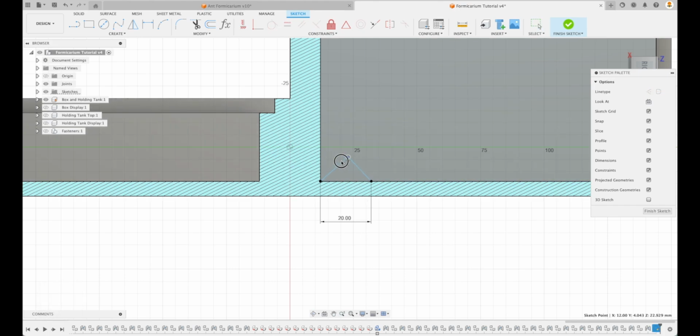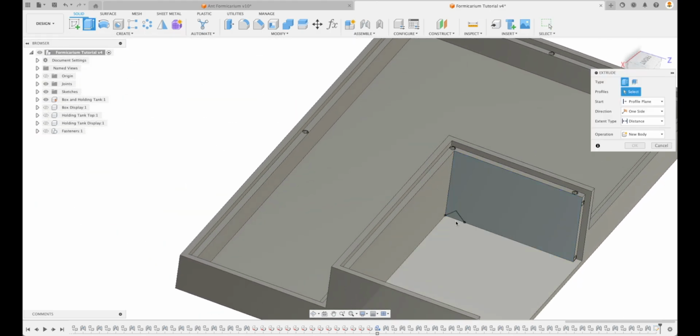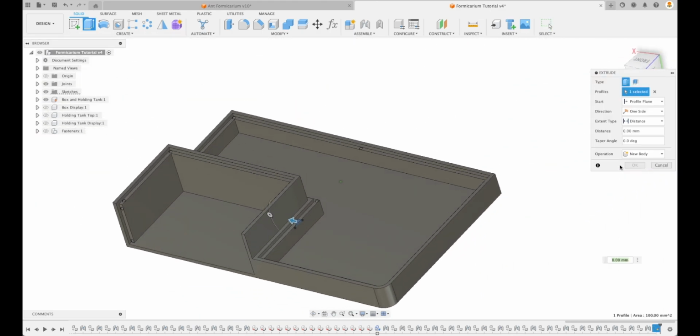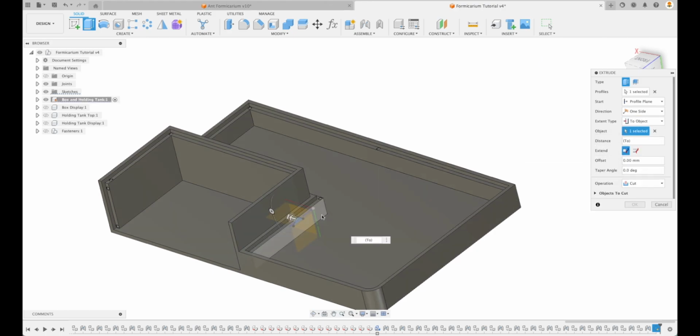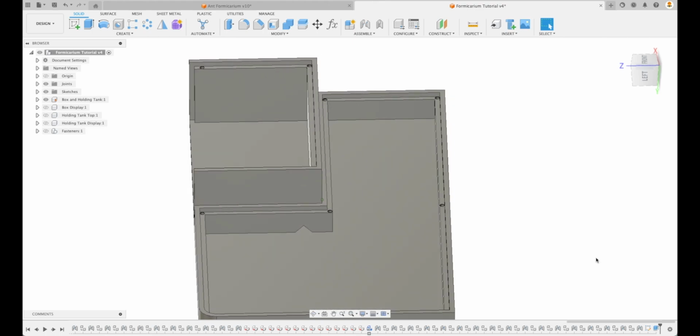And so look at here, we're wondering what needs to be constrained. And we just grab a point that's not constrained and move it. So here we're going to create in between there, and we're going to call this 45 degrees. Excellent. Let's just leave it there. Finish. Perfect. And now we should be able to extrude this all the way through to the other side. Let's go to Object. Boom, right there. That should be big enough for the ants to go through. That's excellent.